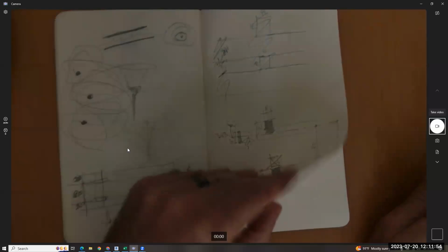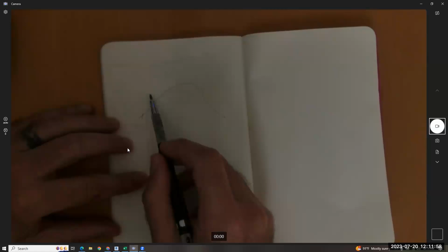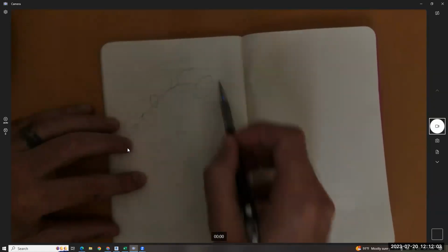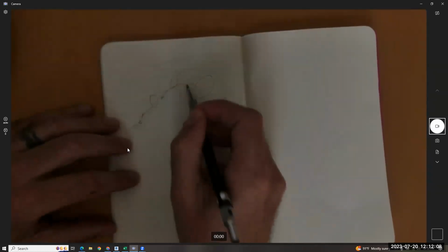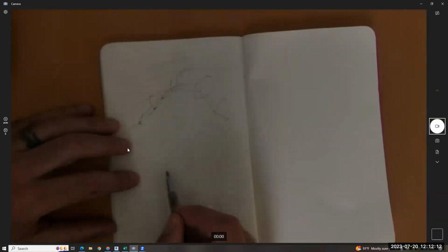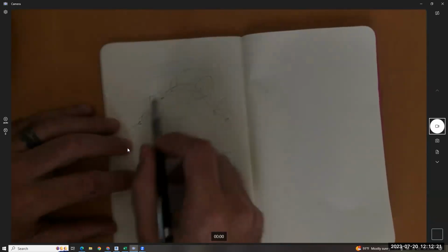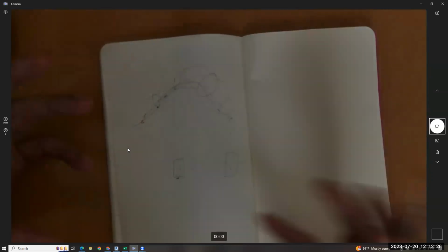If you want to be able to snap a whole bunch of points and have a weird form with different cross sections on it to make a different shape, then you have to use the generic model adaptive. You set points, you draw a spline on there. You also set points, and then you have to make a generic model adaptive with a single point and the profile on it. So you have to draw the profile, load it onto a point, then load it into this, but you could have crazy different cross sections that are making really crazy forms.